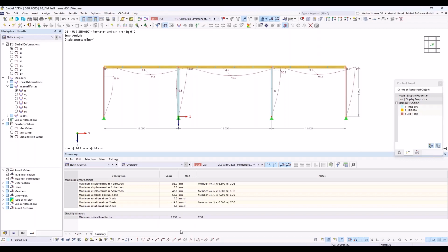But what I already mentioned, for the stability design using the classic equivalent bar method, meaning method C, the internal forces can be calculated according to geometrical linear analysis, and buckling lengths must be assigned to the columns. But for the design of the lateral torsional buckling, the application of the second order analysis is also required with this method.